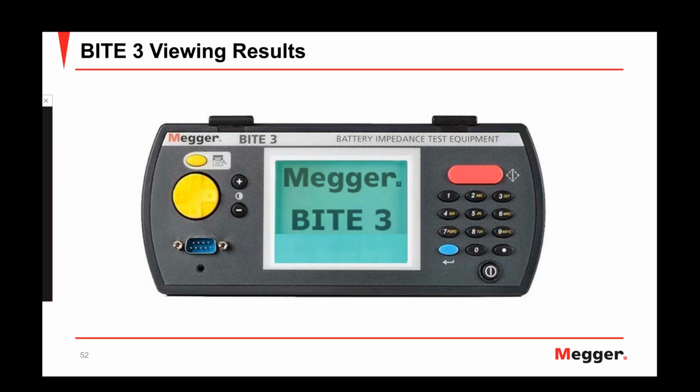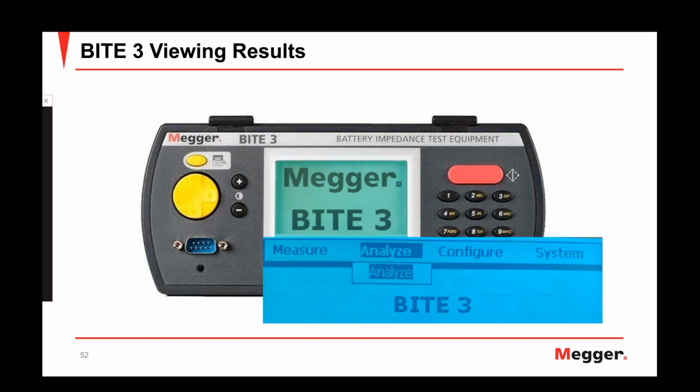Now, for viewing your results on the BITE 3, you're going to utilize the LCD screen on the transceiver or download your results using PowerDB software. So to be able to view the results on the transceiver, go ahead and use the crosspad to select and highlight the Analyze option, and then press the Enter button.